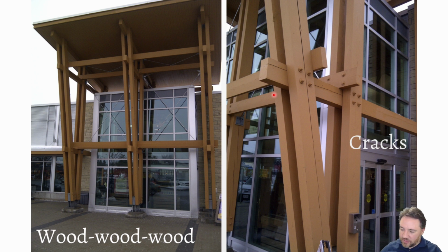You can see that we have a bit of a problem with this connection to do with shrinkage. You can see these cracks. We have a crack at the center of this member. We have a crack at the center of this member. And this is due to differential shrinkage. So remember that timber shrinks much more in the perpendicular to grain direction than it does in the parallel to grain direction, right? It's more than an order of magnitude less in the parallel to grain direction. So let's say that the parallel to grain direction was 0 for the sake of argument. Let's say it didn't shrink, and only this dimension shrinks across the perpendicular to grain direction, because that one is much, much more.